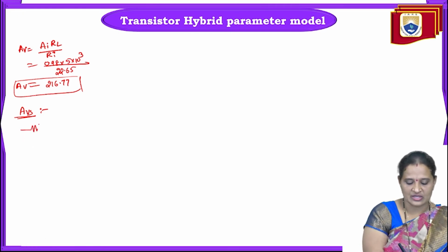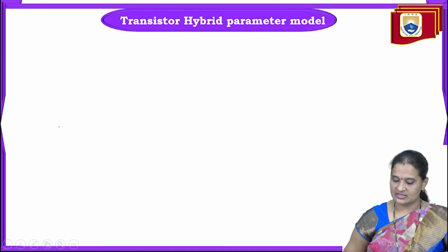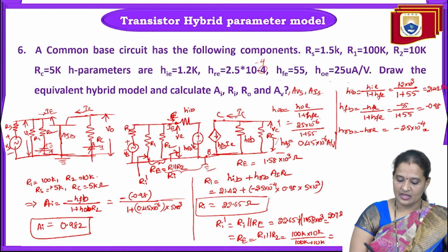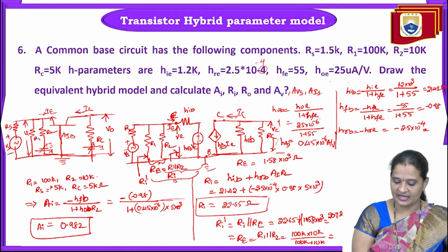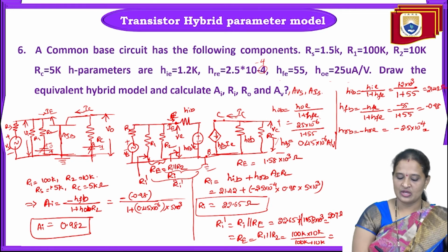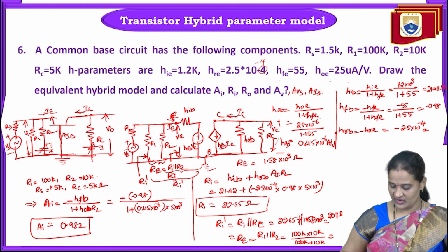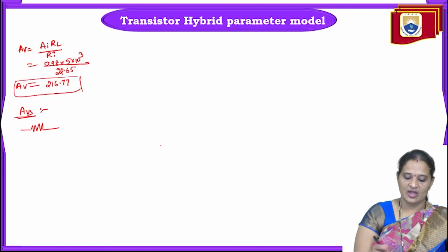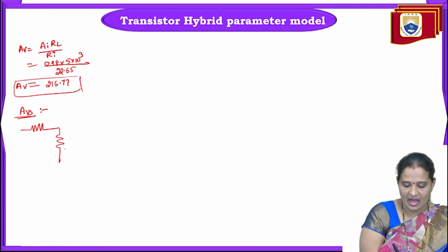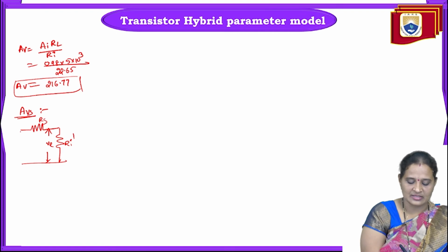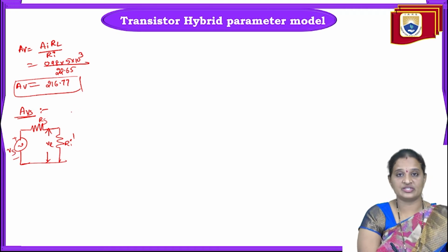If you look at this diagram, I can replace this entire circuit with RA dash, where RS will be in series with RA dash. The voltage measured across RA will be VE, and this is RS, and here is the voltage source Vs. Now apply the voltage divider principle.